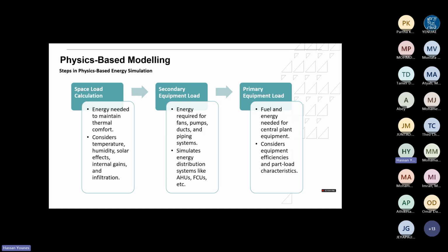It doesn't mean that it will confirm thermal comfort, because we're not designing the building when we're doing energy modeling. There's someone doing the mechanical design. As an energy modeler, I'm not designing the building. I could be the same person doing both, but if I'm doing the energy model, I'm just assuming that I'm going to have probably that temperature. The software will calculate that, but it doesn't mean that I will get thermal comfort. There's another method to look at, maybe we'll look at that at the end of the presentation. What is the method to do thermal comfort modeling? That's something else. But what is the energy to maintain a certain temperature and a certain humidity level?